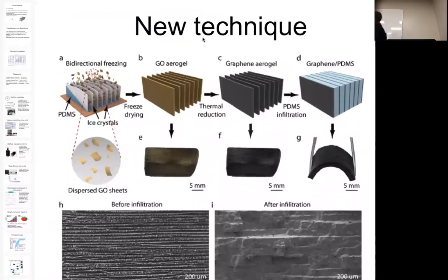So, kind of crazy. I've done a lot of freeze casting myself, and their way to do it is kind of weird. You take a copper plate, and then you cast a wedge of silicone. Okay, so the wedge acts as an insulator. And then you put dry ice or liquid nitrogen on the bottom here. You pour your solution in the top, and so it's freezing from this point in this direction and that direction, up and over at the same time.